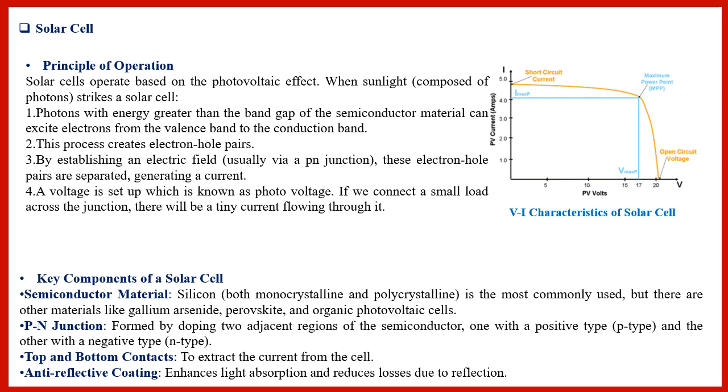When the light reaches the PN junction, as we may see here, the PN junction being shown in the earlier slide, light photons can easily enter the junction through the thin p layer. That's why we have made the thin layers of small thickness, so light can easily be incident through that thin p layer. The light energy supplies sufficient energy to the junction to create a number of electron hole pairs.